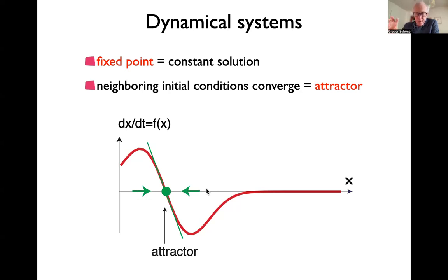In multiple dimensions it might be a little ball, and every initial condition inside that environment converges in time, as time increases, to that fixed point. That's called a fixed point attractor. And that's what we're dealing with as the states that are going to generate behavior, control behavior. This is what control theory does for the physical control of the robot: make sure that around the set points are attractors. This is ensured by the real part of the eigenvalues having negative value.